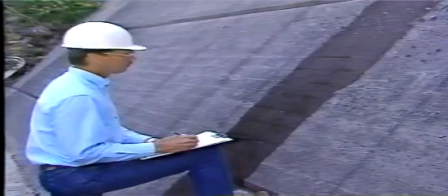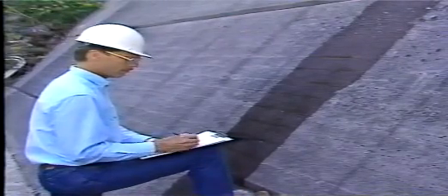Efflorescence may cause cracks or joints to widen, leading to faster deterioration and increased leakage. However, in some cases, the deposits may seal the crack against additional leakage. If leakage has increased or appears at a new location, note the amount of flow. Also, record the location of new leaks.